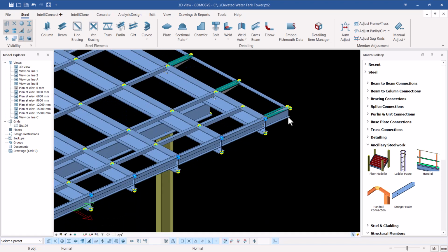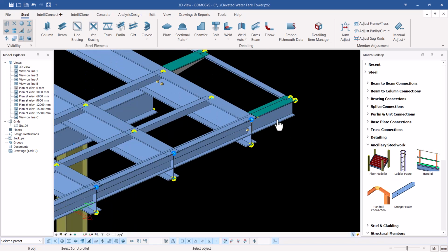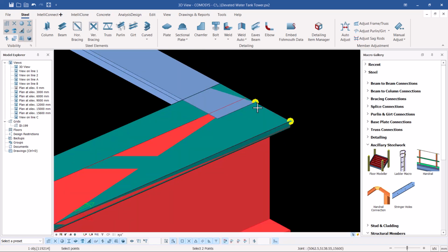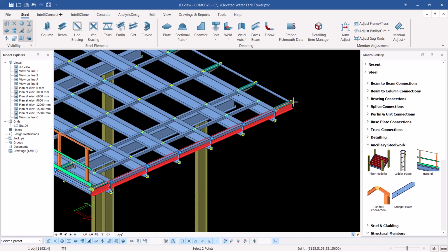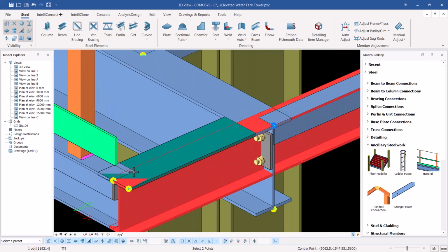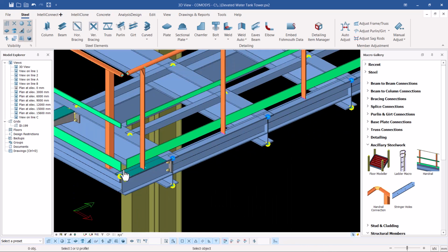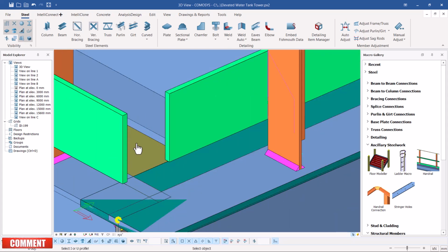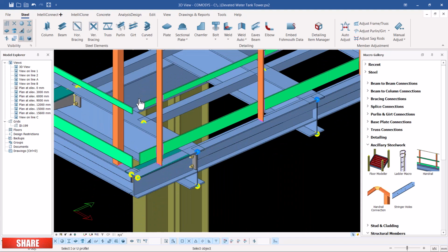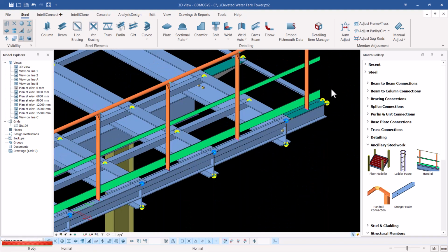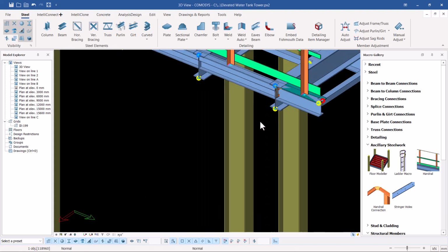So I'm going to pick that member, right click, right click once again, snap at the edge there, move all the way to this far end and click on that. So we have our handrail in place. You can see there's some variance here which might bring some difference, but that should not worry us. We want to create the handrail and we'll modify that later on.